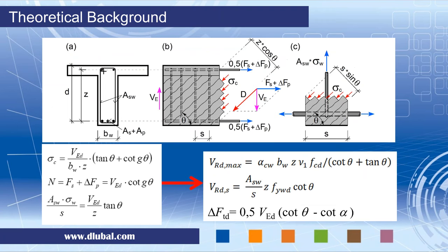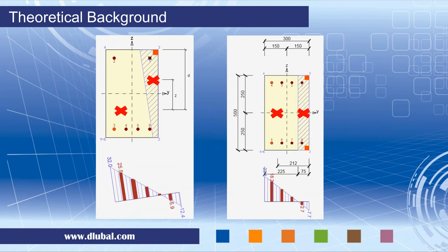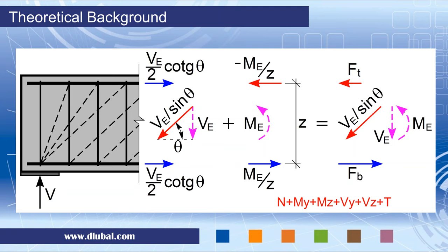We will also touch on the shear analysis, the equilibrium conditions, and how the Eurocode formulas are derived from these equilibrium conditions. What is more, what is the role of the lever arm caused by the flexure in the shear analysis? That will also be a topic. And last but not least, we have a nice feature of interaction of all internal forces. You can see all internal forces here, and this is just an explanatory picture of how you can combine shear force and bending moment.